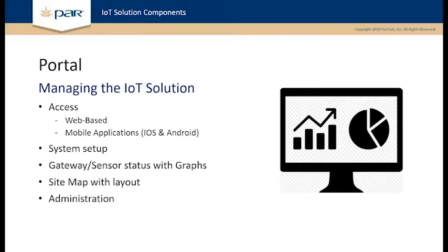I have to note that an IoT monitoring system must allow for a way to take into account these defrost cycles, because when we first got into this, some of our first customers were getting a multitude of alarms based on defrost cycles. So you must take that into account when you're setting the system up. You don't want false alerting. You want to get an alert when there's really action to be taken, when you really have a problem. And that's something we take very seriously.